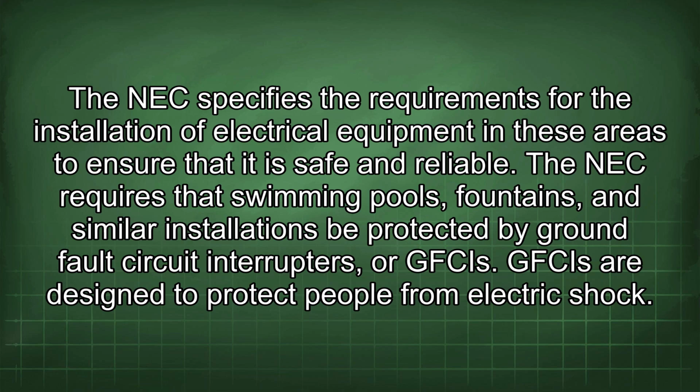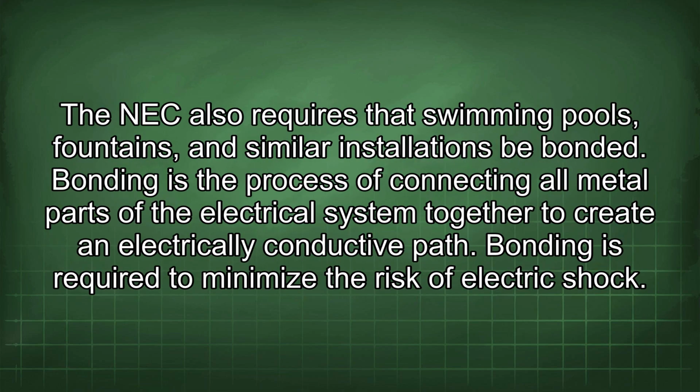The NEC requires that swimming pools, fountains, and similar installations be protected by ground fault circuit interrupters, or GFCIs. GFCIs are designed to protect people from electric shock. The NEC also requires that swimming pools, fountains, and similar installations be bonded. Bonding is the process of connecting all metal parts of the electrical system together to create an electrically conductive path. Bonding is required to minimize the risk of electric shock.